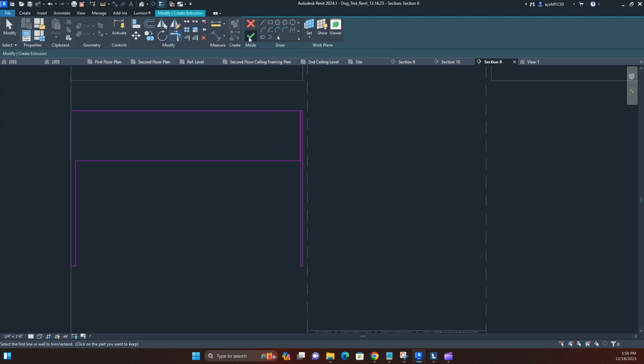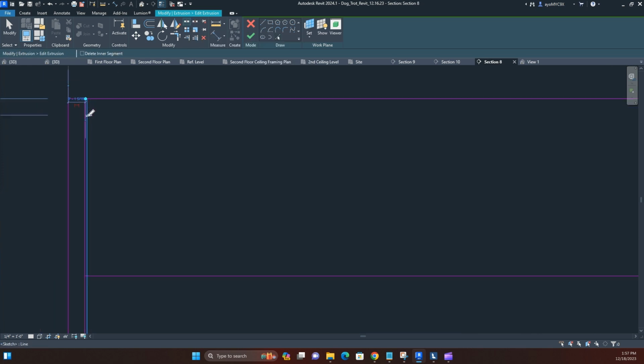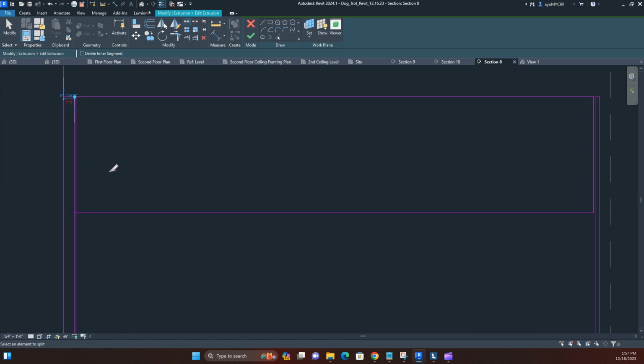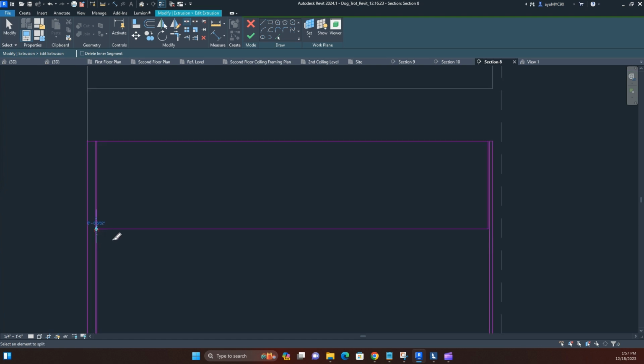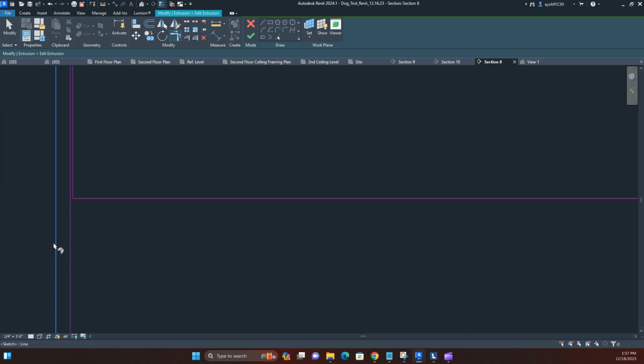I take that all the way up. I give it some spacing, 0.19 inch. Then I try to cut it. Use my cutting tool, cut it at the top. I don't need to cut it at the bottom. Just trim and extend will work, but I'm just gonna cut it. Trim and extend. I have a little bit of line I need to delete. There you go. So it's looking good so far.